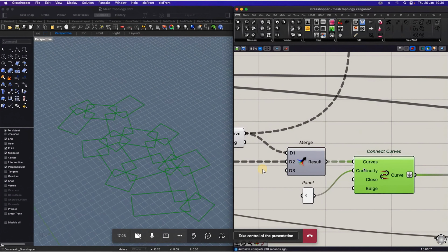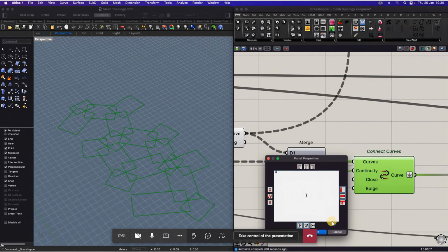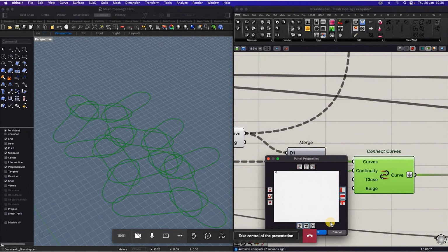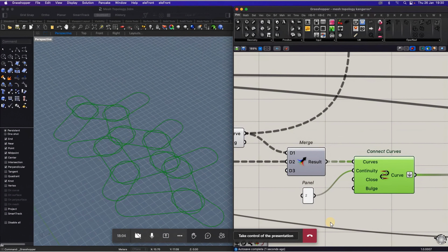What's also interesting is continuity. I'm sure you're familiar with that as well. In Grasshopper, continuity 0 means that your curves are touching. Continuity 1 means it's tangent. So if two curves meet, then they become tangent. And what you call continuity 2 would mean the curvature is the same for both. So actually, let's try that. It should round the edges if we do it as 1. There you go. So continuity 1 is tangent. 2 should look probably very similar, maybe just a softer or flatter curve.